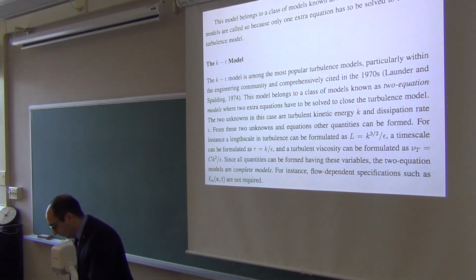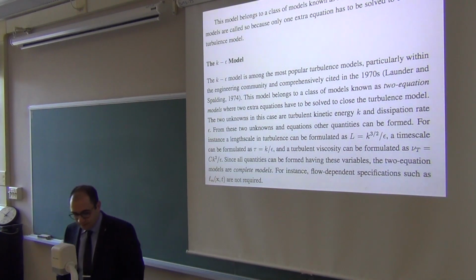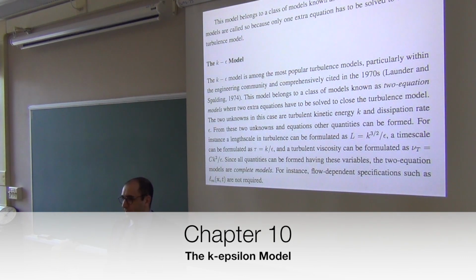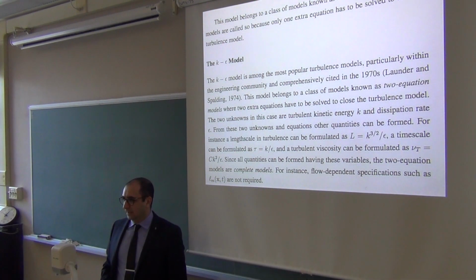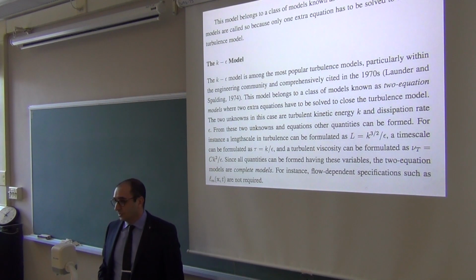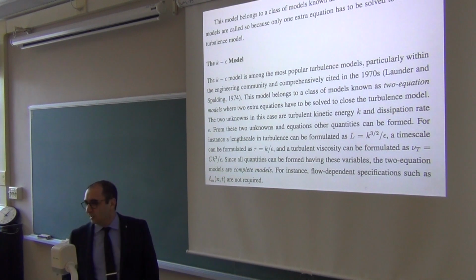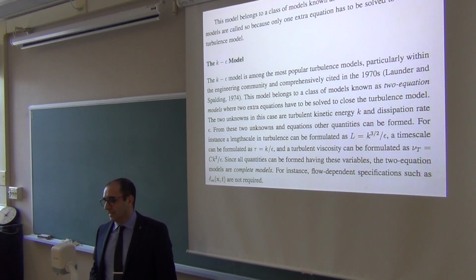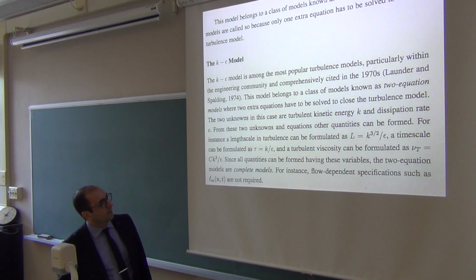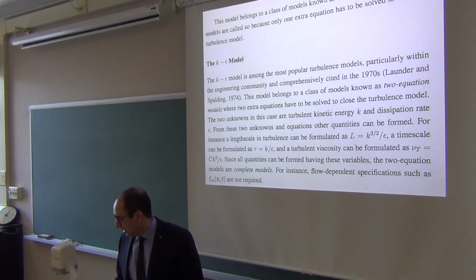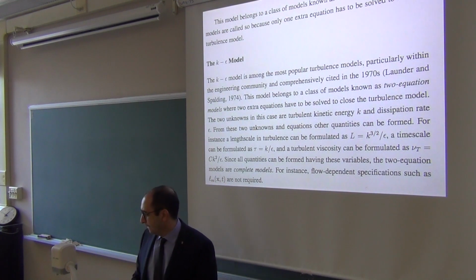So today I'm going to introduce to you another model which is a two equation model known as the K-epsilon model. How many of you heard of this model, K-epsilon? Raise your hand. This is probably the most widely used turbulence model out there. It's optimized in many different smart ways, so it generally works for a lot of problems and gives you a practical answer. However, sometimes it fails horribly for given types of problems. So you have to be very careful where and when to use it.